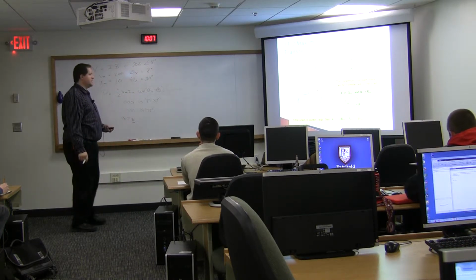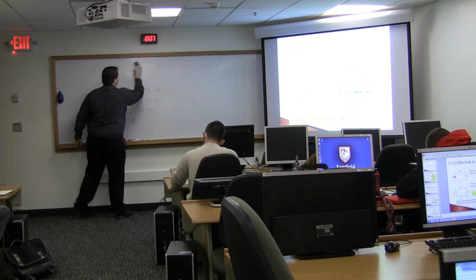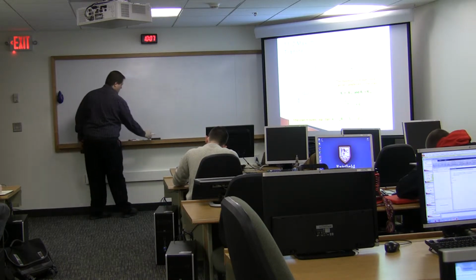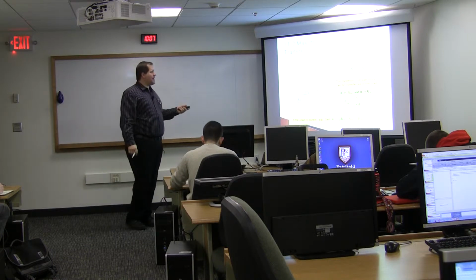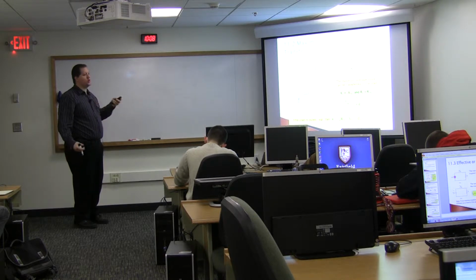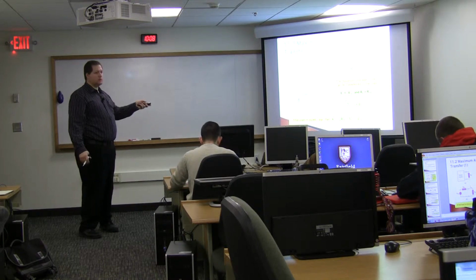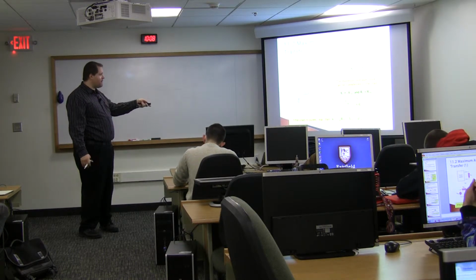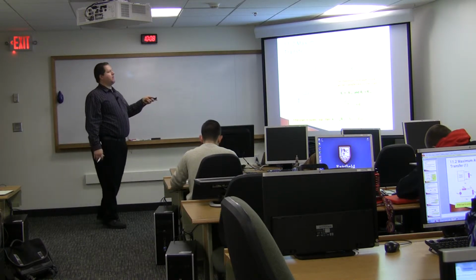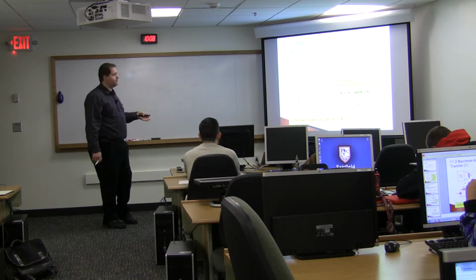Maximum average power transfer. This, as I mentioned, is related to the Thevenin or Norton equivalent circuits that we did back in chapter 4. With maximum average power transfer, we're looking to figure out what the impedance of the load should be to get the most power we can out of our source, our linear circuit, which is our Thevenin equivalent circuit, a voltage supply in series with an impedance. That will allow us to get as much power as possible transferred into our load impedance.